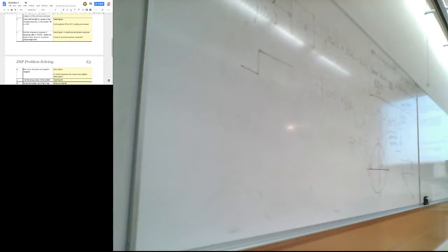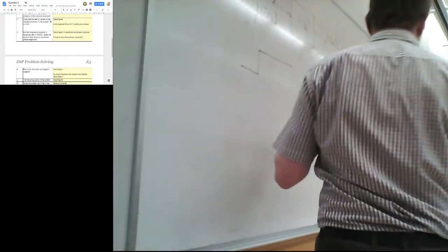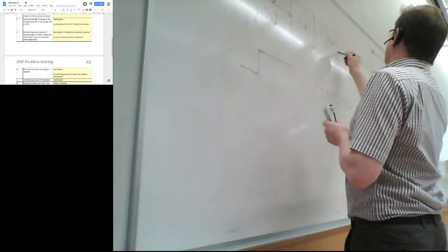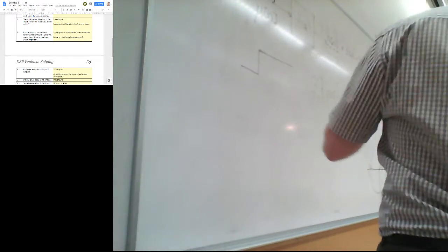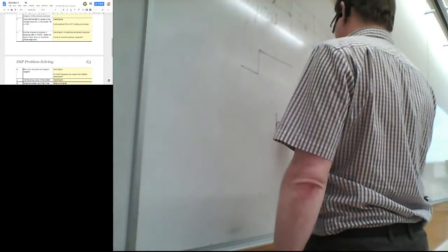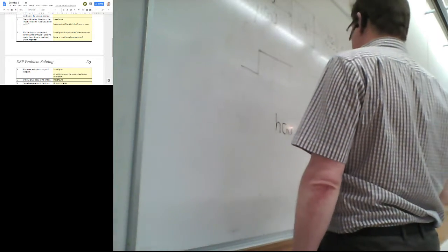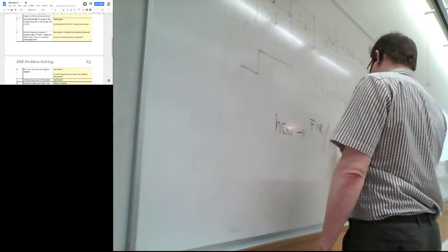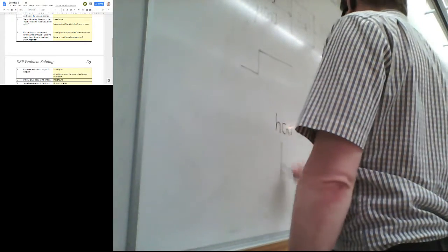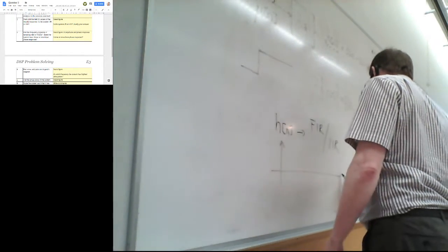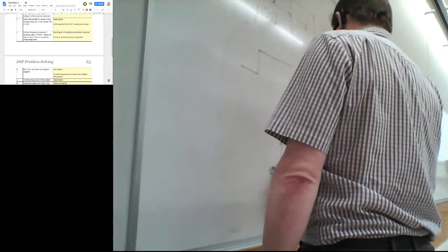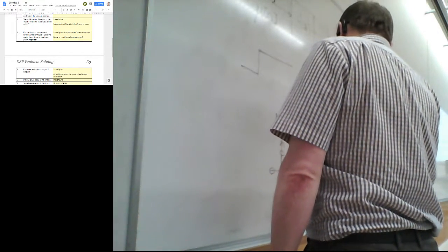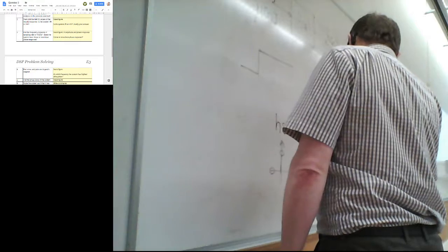Okay. I kind of skipped one thing. How about this impulse response? Impulse response basically will tell you if the system is FIR or IIR. The only thing you need to do is observe the impulse response, and see whether it ends or not.